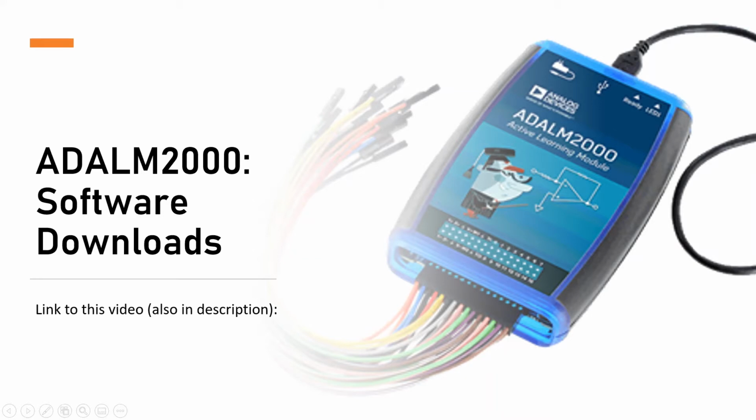Prior to plugging the M2K into your laptop, it is crucial that you first install the required driver software. Additional application software called Scopy is also required so that you can use the instrumentation functions of the device. A link to the necessary software and some basic download instructions, along with an instructional video, is provided in the description of this video. Once the software is properly installed, the M2K can be connected to the computer via the provided USB cord.